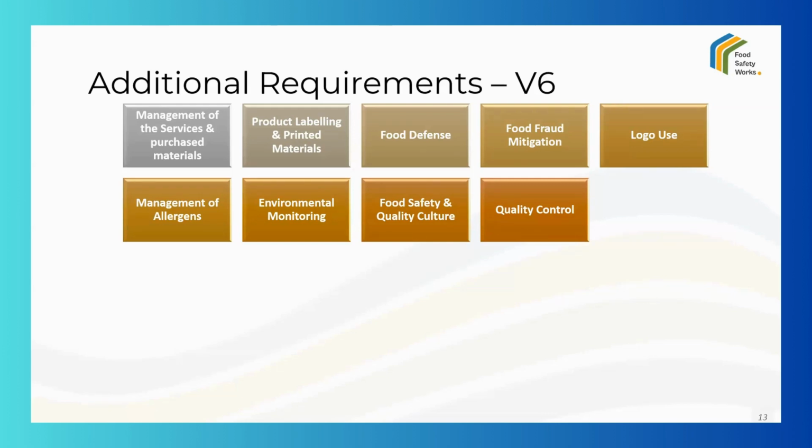This should also include that all the equipment you have is calibrated and verified so that there are no deviations. There has to be a procedure written down so that line startup and changeover procedures are established and implemented to ensure products are meeting the requirement.